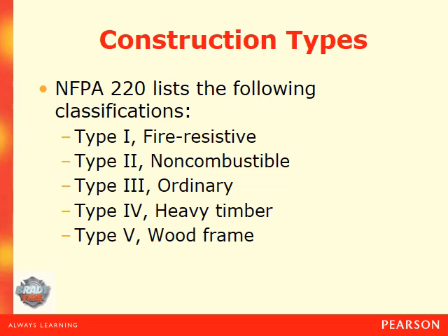And then your type 3 is your ordinary construction, known as Main Street America. It's kind of like the retail type construction that you would see old-timey going down, of course, Main Street, with the residences above. And then your type 4 is your heavy timber or your old mill style construction. Churches are an excellent example. And then your type 5 is your residential or wood frame structure.